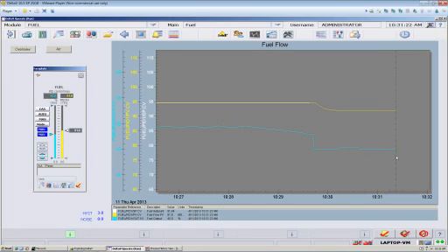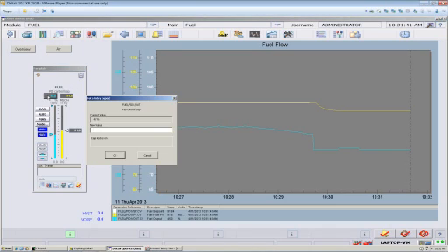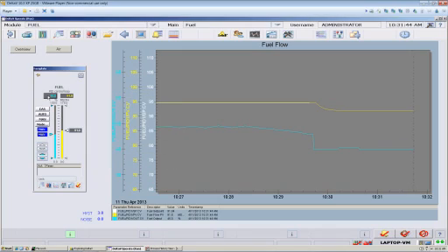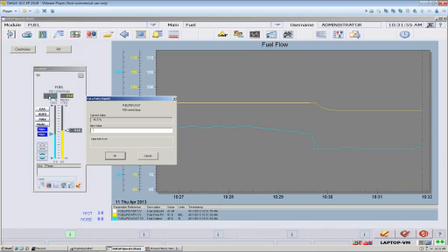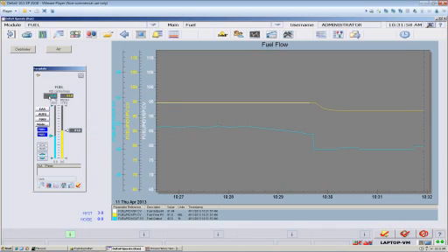Another place this can happen is in electric motor actuated valves. They have intentional hysteresis built into them, so the valves aren't constantly saying small open, small close, small open, small close. Sometimes if they're close enough, the electric actuators just choose to be good enough with close enough. But my next step is I would try a 0.5% change, and I would keep moving up and down with gradually bigger changes until I find how big of a change I need to make before I affect my flow.